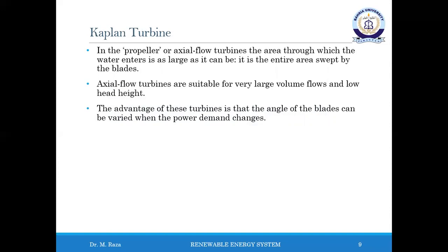In case of axial flow, there is no need to feed the water in from the side. It might appear to be better to let it flow in along the axial axis instead of deflecting it through a right angle. But if the water flows in along the axis of the turbine, the generator will get in the way and it will get wet.